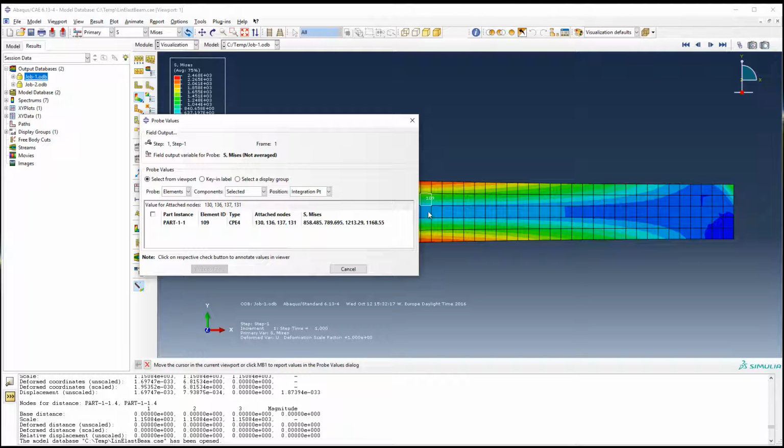Okay, so we computed the stresses at these integration points. What we do then, or I mean, we do it if you do it manually, but Abaqus does it for you, is compute it in the centroid. So you can look here. This is the centroid, and if you just look at this lower left corner here, you can see that it's 27.8567.